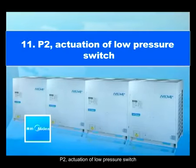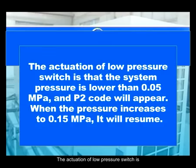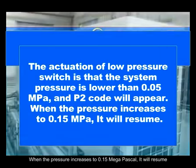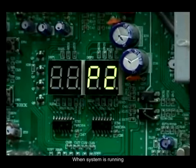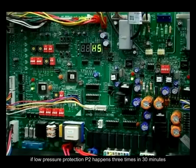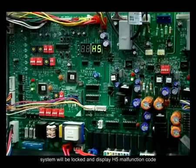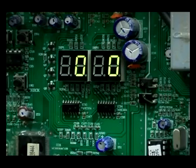P2. Actuation of low pressure switch. The actuation of the low pressure switch is when the system pressure is lower than 0.05 megapascal, and the P2 code will appear. When the pressure increases to 0.15 megapascal, it will resume. When the system is running, if low pressure protection P2 happens 3 times in 30 minutes, the system will be locked and display the H5 malfunction code. Only after restarting the unit can it be solved.